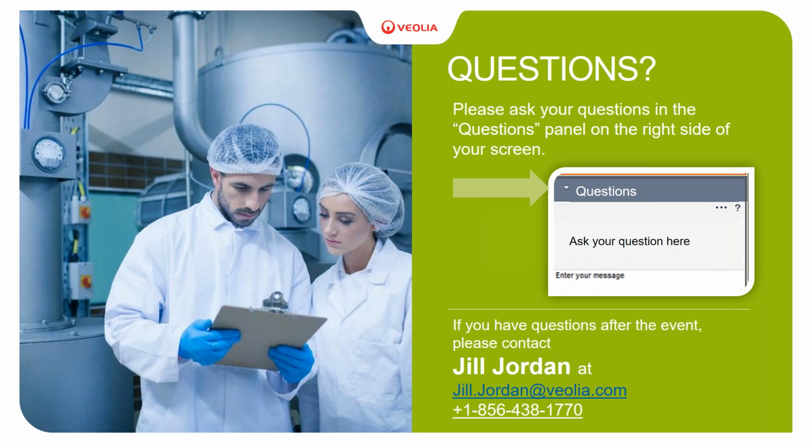Great. Leaving the sludge discussion, we have some other questions here about micronutrients. Can you talk about how important it is to add micronutrients to a reactor in terms of operating one? Micronutrients are very important, especially in nutrient-poor wastewaters. In the food industry, unless it's a condensate we're treating, they have a lot of the micronutrients that are required by the bacteria.